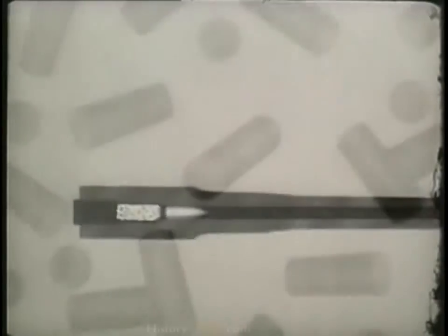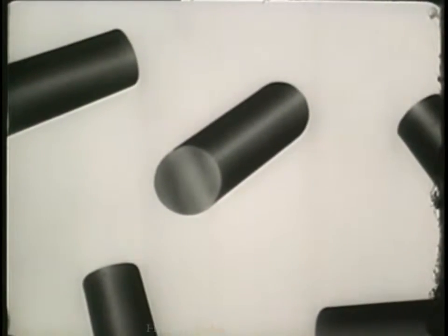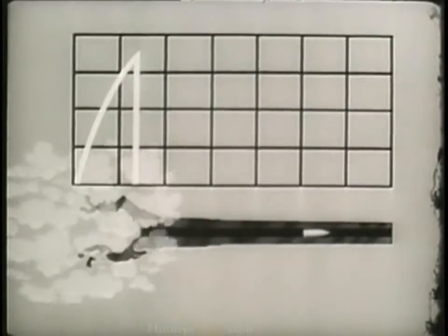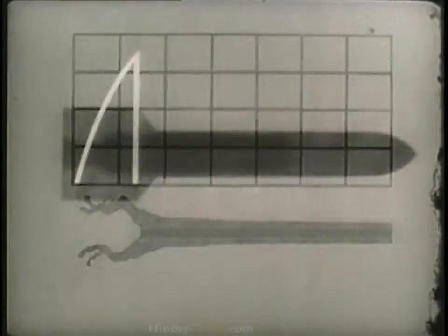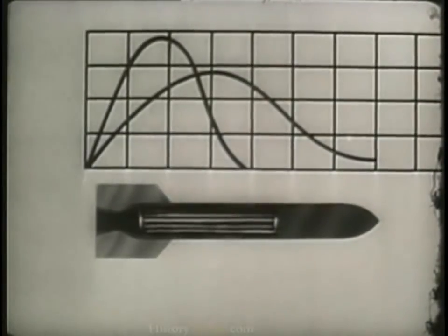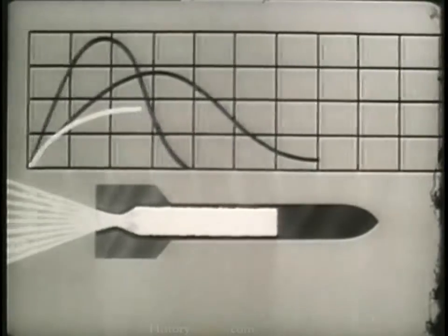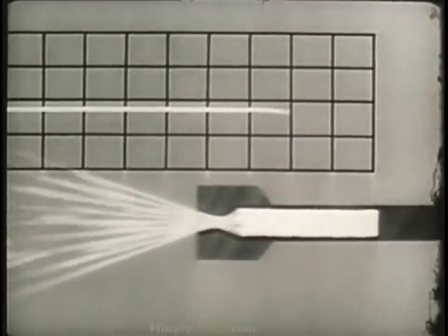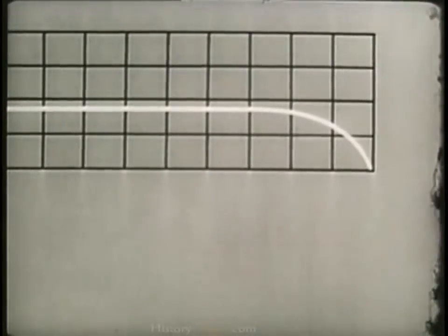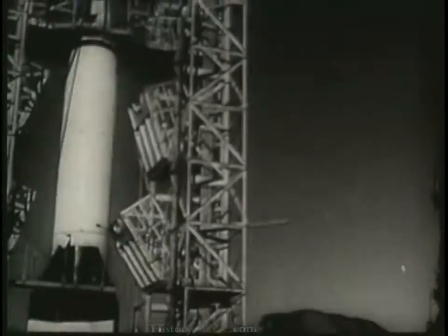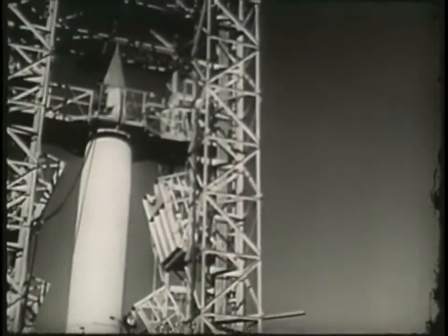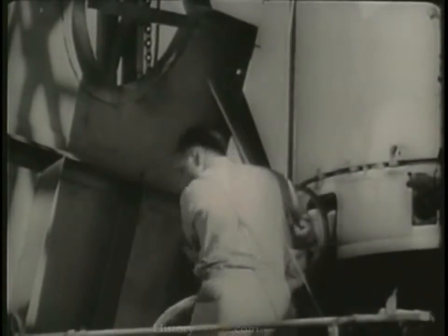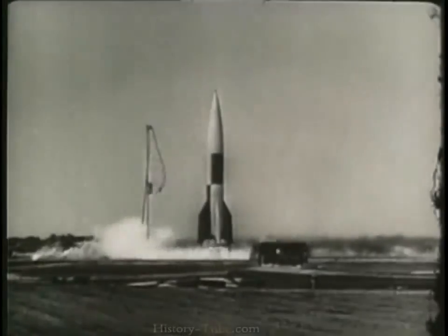But if we use digressive grains in a long-barreled gun, there's a chance that the higher maximum pressure produced will blow it up. For a rocket, we need a low, steady pressure, so we use a special neutral grain. The low pressure will not burst the lightweight rocket, yet give smooth acceleration. For the V2 and other large rockets, it's better to use certain liquid propellants, mixing them at a constant rate to assure constant burning.